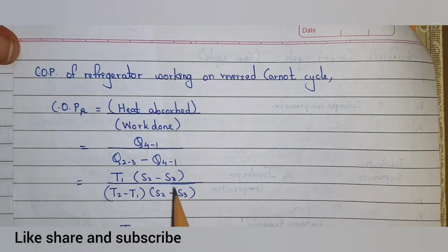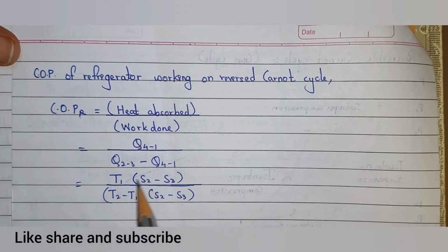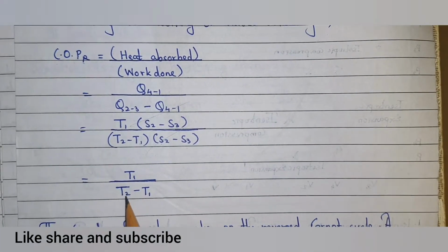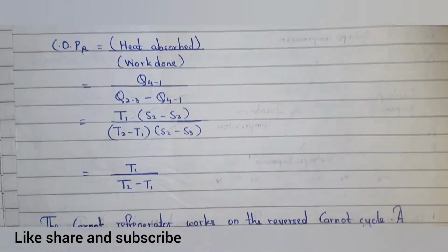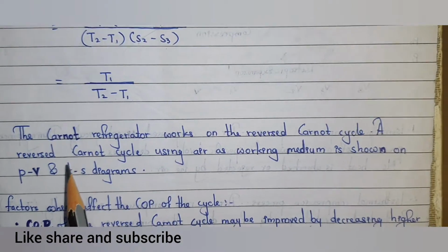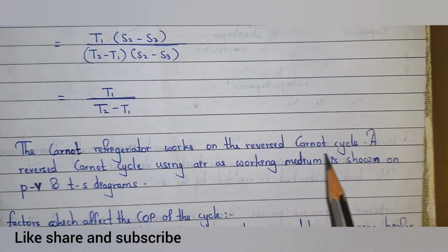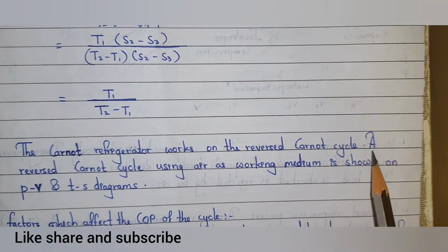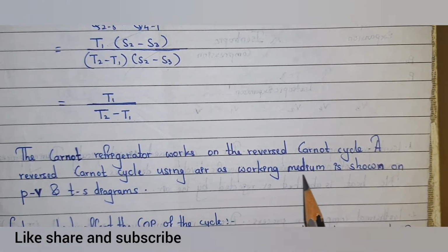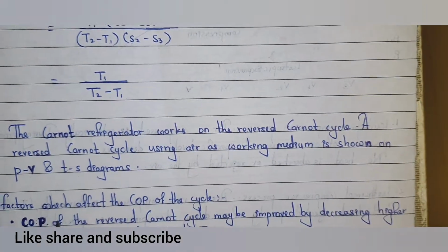Here (S2 minus S3) is common, so we can cancel it out. So now we get T1 divided by (T2 minus T1), that is the difference between temperatures. The Carnot refrigerator works on the reverse Carnot cycle. A reverse Carnot cycle using air as working medium is shown on the PV and TS diagrams.